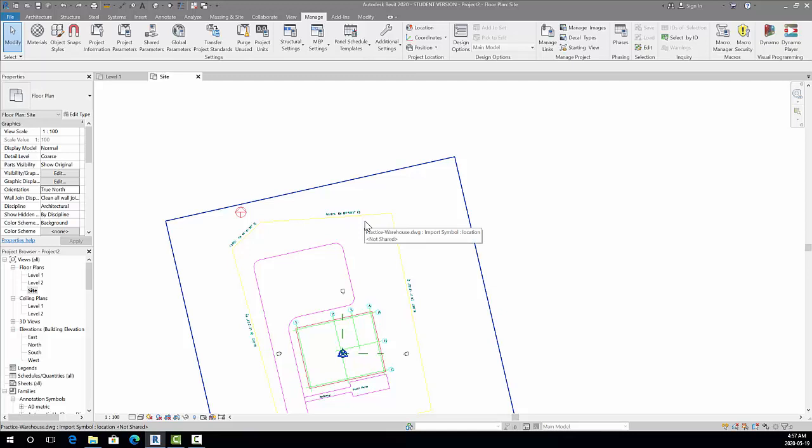Perhaps you started the project by designing the house, and then you brought your property lines in. If you do it that way, then your true north might not actually be straight up and down on the page, so you might actually need to reset your true north in that situation. The other reason you want to have true north set accurately is because it will affect your lighting. When you have the sun casting shadows on the building, you do want your orientations to be as correct as possible. So you do want your true north to be set in the proper direction.